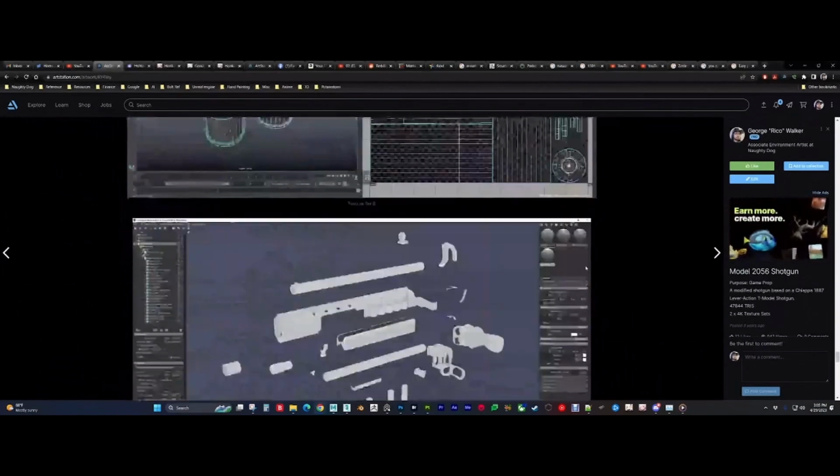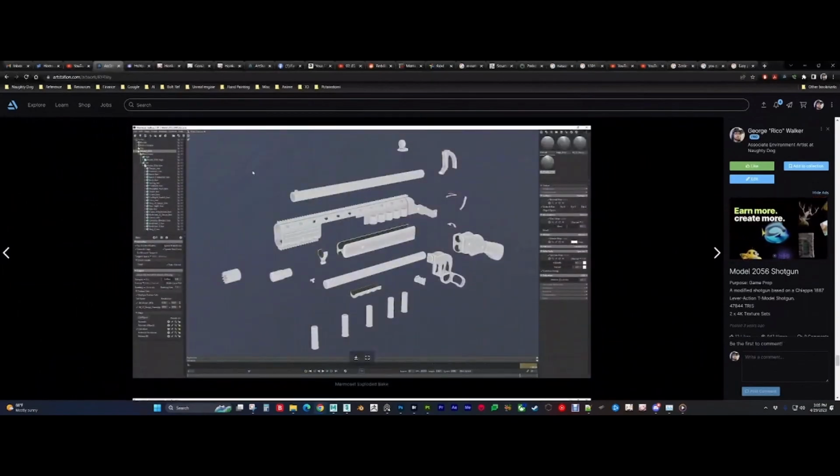Yep, there it is. So what I would do is an exploded model that I would import, and then I would have the low and then the high poly on it, and I would bake it this way, just in the individual parts, because I got around the thing where you have the back faces interpenetrating and it's making shadows. So that's how I got around that. That's just one way of doing it.